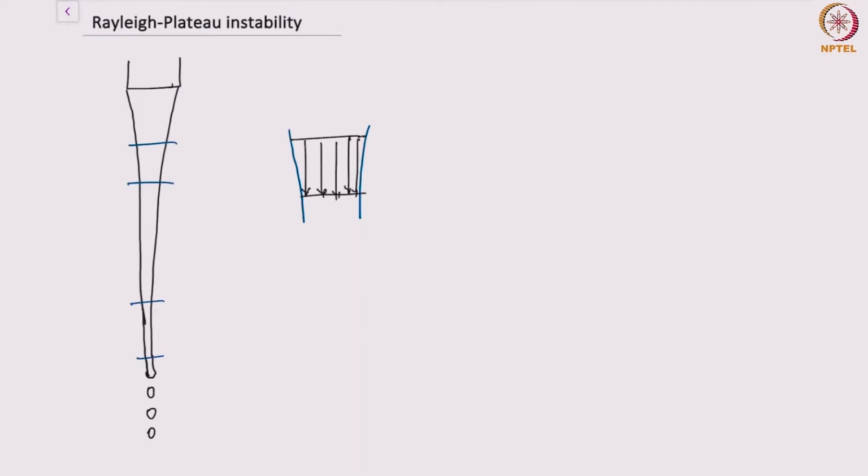The reason is that in this problem we are assuming that the surrounding gas is passive and has no viscosity. Therefore, the tangential stress boundary condition simply reduces to the statement that the shear stress at the interface is 0, and at leading order you get a plug flow.